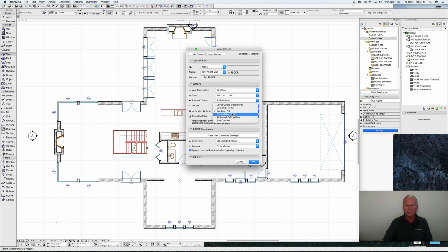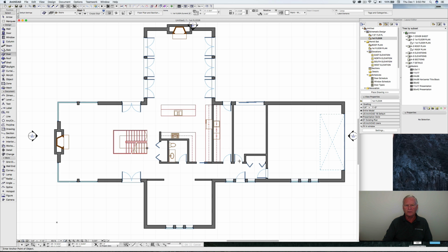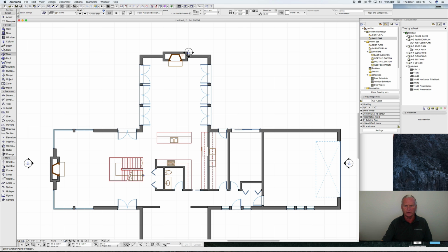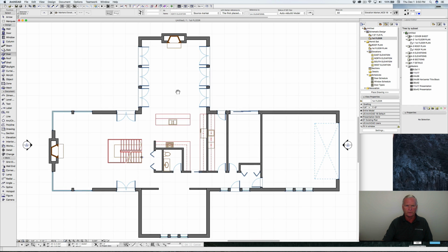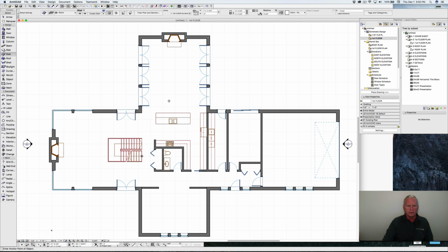This comes this way. We're going to click on that, and what that's going to do is, under a setting that is set up for presentation solid, these markers are going to go away and those walls are going to go solid. And that looks, I think, a lot more like a preliminary design. If you note up at the top here, we have that one marker in our way. We're just going to hit the shift key, click on it, go Control D, drag it up a little bit and get it out of our way. Okay, click off of it.